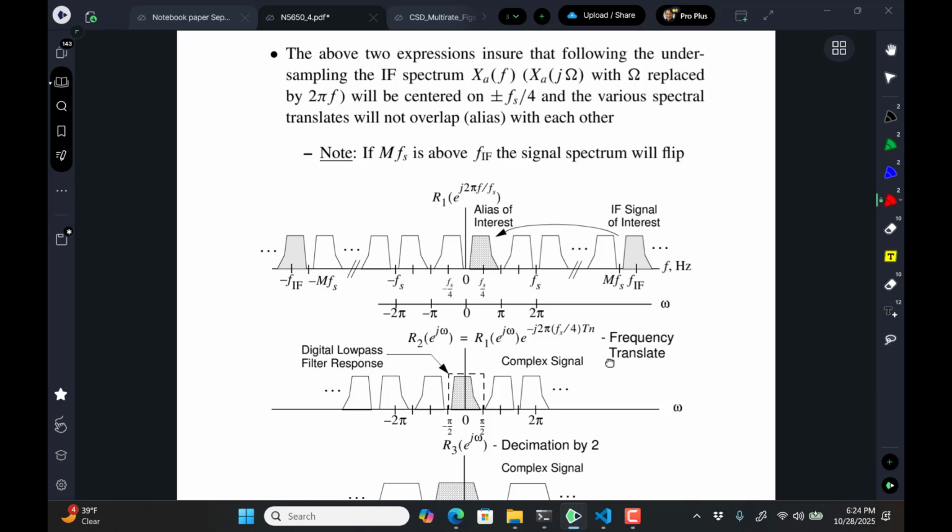That can happen if there are sidebands and other things encoded onto the modulation. TV waveforms, for example, have traditionally been what's called vestigial sideband, where the signal has a carrier, but most of the information is up at the higher end or below the carrier. And even though the newer TV signal is purely digital, it still uses this vestigial sideband idea.